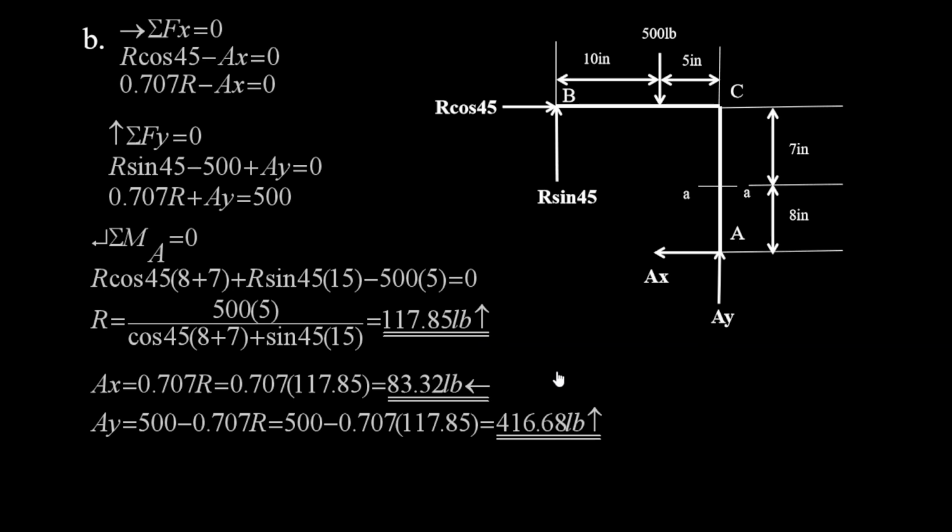And then we know our area. They said the pipe is 1.5 by 1.5, and it has a thickness of 0.5. The hole will be 0.5 by 0.5. So it will become 1.5 squared minus 0.5 squared to give us our area. Basically, our change in length is what? Force times our length over E times A.